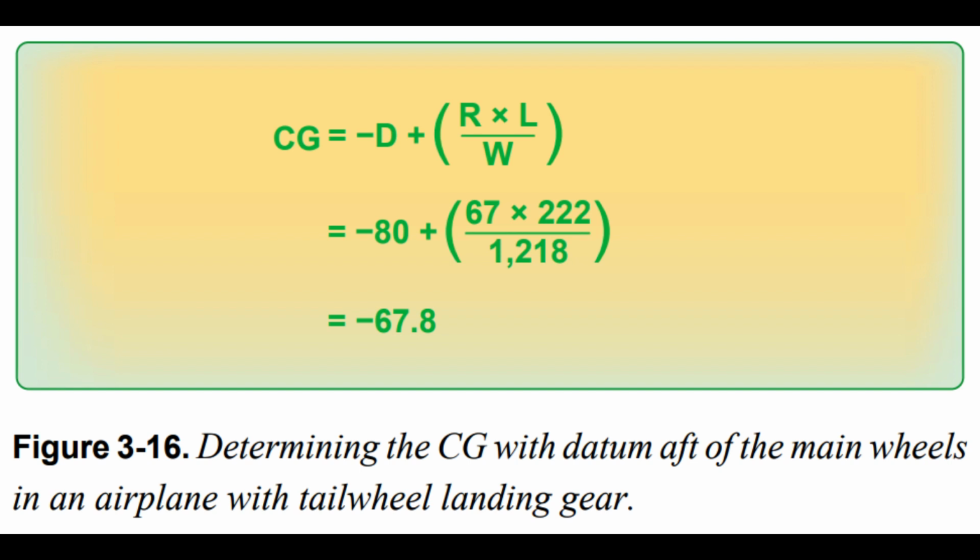the aircraft's maintenance records. For the purpose of weight and balance computations, the CG of an airplane is an imaginary point about which the nose-heavy moments (minus) and tail-heavy moments (plus) are exactly equal in magnitude. If suspended from the CG point, the aircraft would have no tendency to rotate nose up or nose down. The CG of the loaded aircraft can range fore and aft within certain limits that are determined during the flight test for type certification. These limits are the most forward and rearward loaded CG positions at which the aircraft meets the performance and flight characteristics required by the FAA.